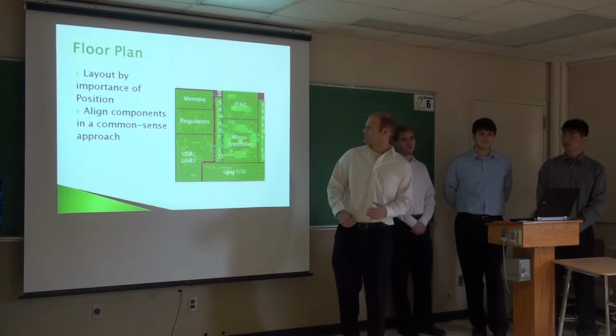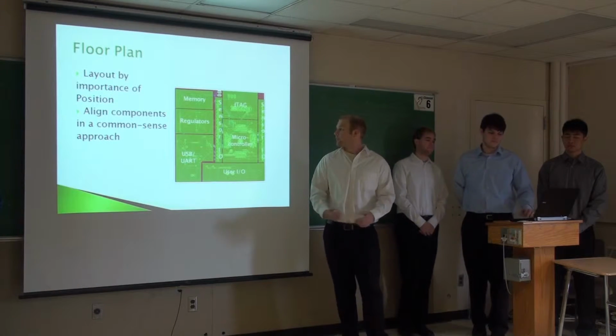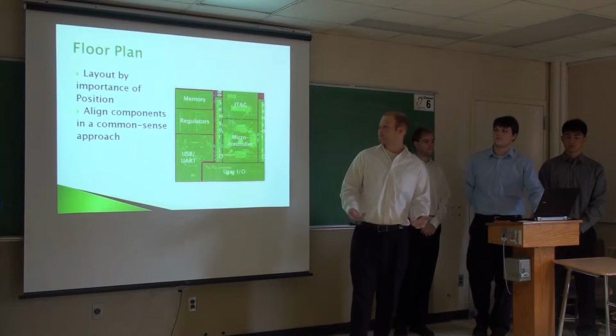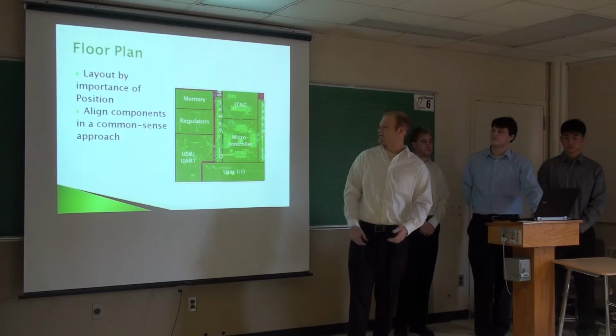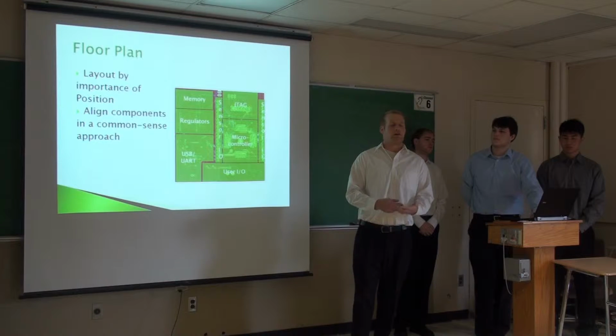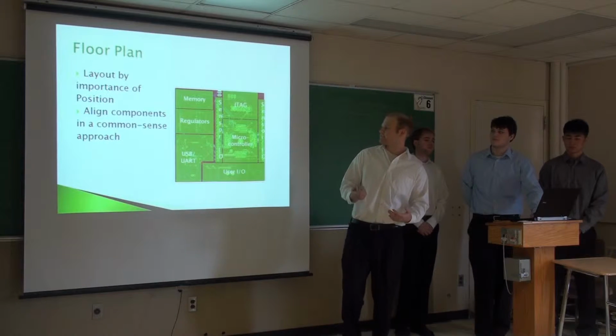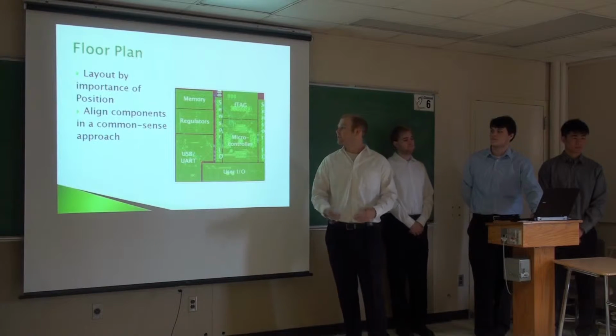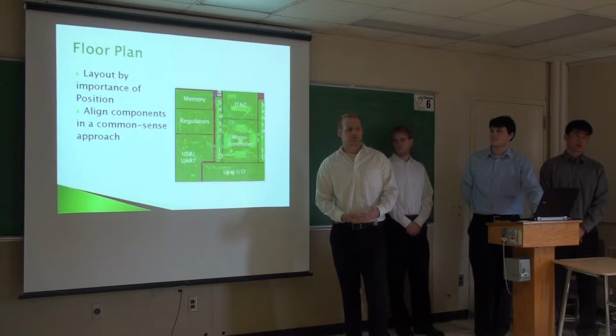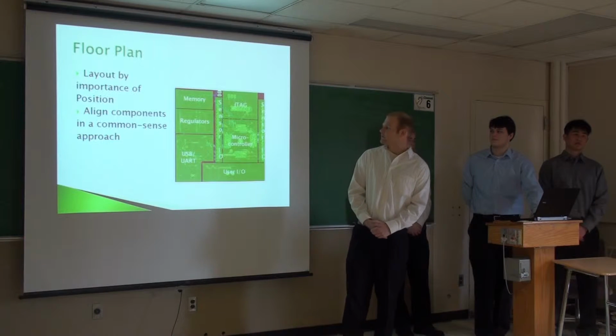And same with our sensor I/O. For our microcontroller and our JTAG, those are going to be talking to one another, same with everything else. So they connect, put near each other. And you want everything to be space efficient. You want the smallest board possible. So as you can see, there's no space wasted here. So this is a good example of good layout.